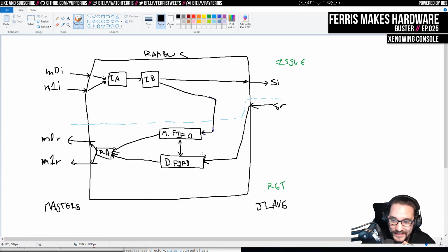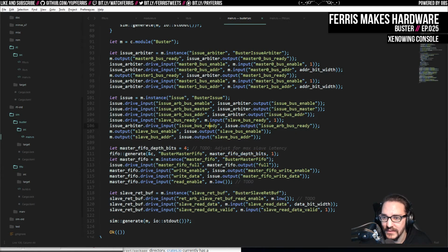We don't need to watch the full signal of this data FIFO, because this FIFO potentially becoming full will stop us from issuing, which will end up filling up this FIFO too. The data flow here is really clear, because we're always issuing across both these channels, and this gives us a skid buffer while we wait for the data to come back. I think this is really good, you guys.